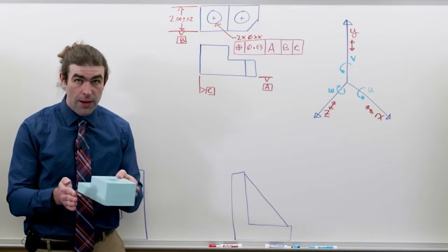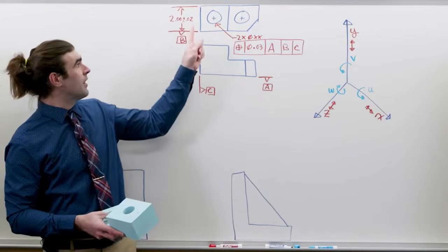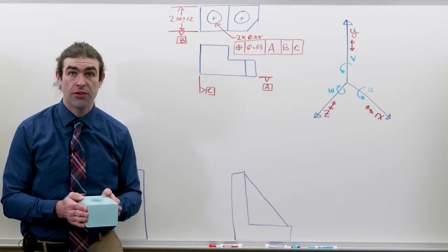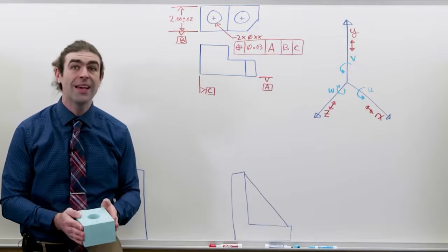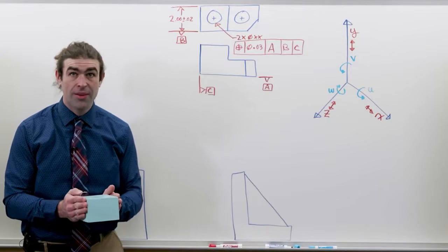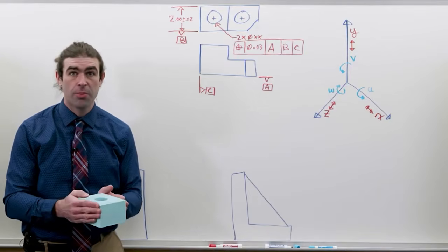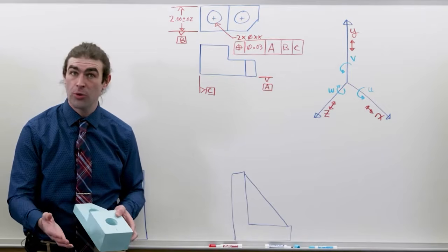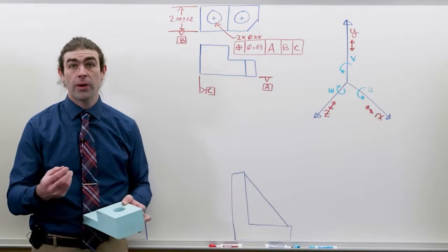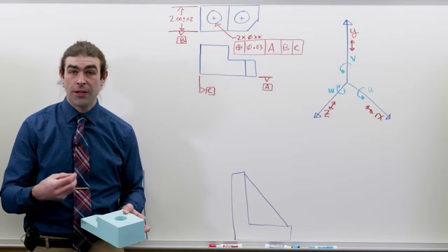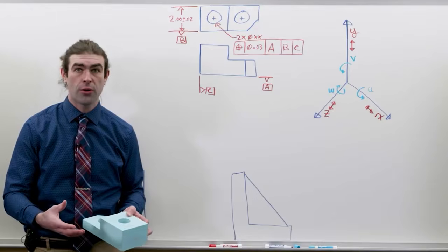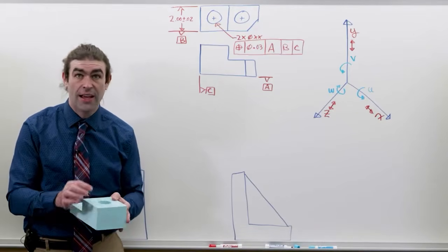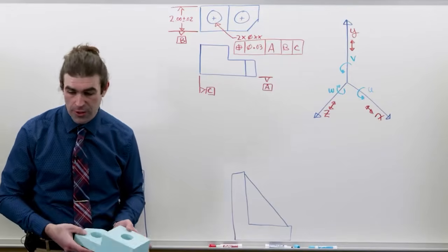You could just set two angle plates 2.02 inches away, so the MMC of that feature or the virtual condition if it applies, and then measure from the center of those two angle plates. The part could move around between them. Okay? It's a little bit more complicated to set up, but what it allows you to do is have something like a robot check parts for you, because now you have fixed gauging. You don't have to center the vise and then find the middle. Okay?